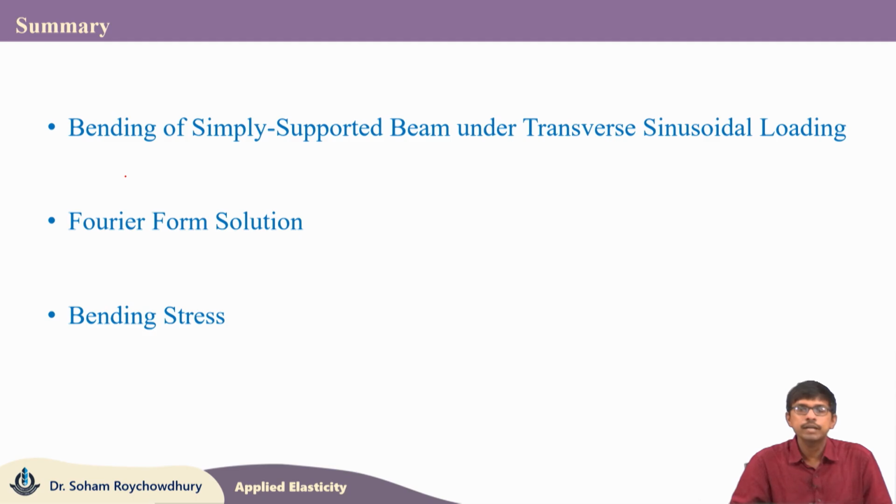So, in this particular lecture we talked about the simply supported beam subjected to sinusoidal loading, and instead of the polynomial form of solution we used the Fourier form of solution. Using that we obtained the stress distribution: we got the expressions of sigma xx bending stress, sigma yy and transverse shear stress tau xy using the Fourier form of stress function.